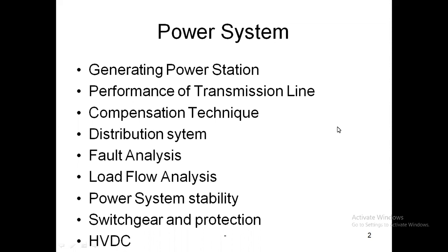After fault analysis, there is another important chapter which is known as the load flow analysis. In the load flow analysis, it is simply solving nonlinear equations. There will be lots of nonlinear equations in the power system. If we have a big power system in which there are lots of buses, and we have to find out the operating condition of that power system, then we will go with the load flow analysis.